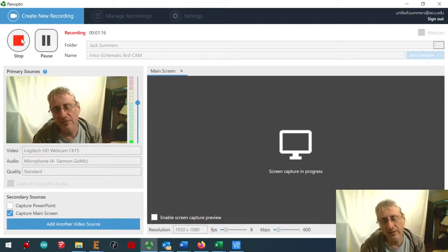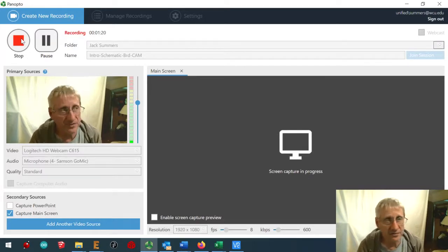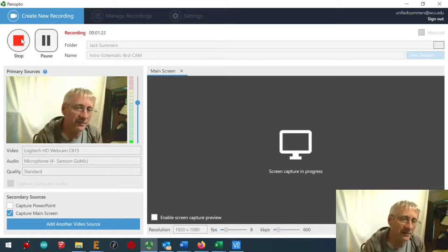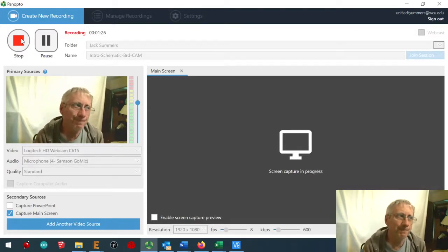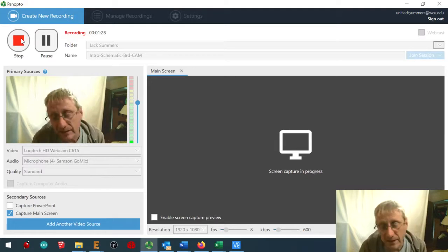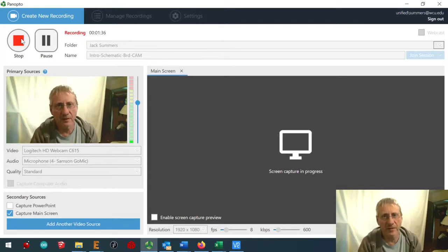One thing I forgot to do while I was recording this was to run a design rules check. And that's an important thing to do. Make sure that all of the design that you set up in the schematic is actually faithfully followed and you don't have any problems. Okay, so I forgot to do that while I was recording this, but yeah, do it in the future, okay? All right, so here is the video.